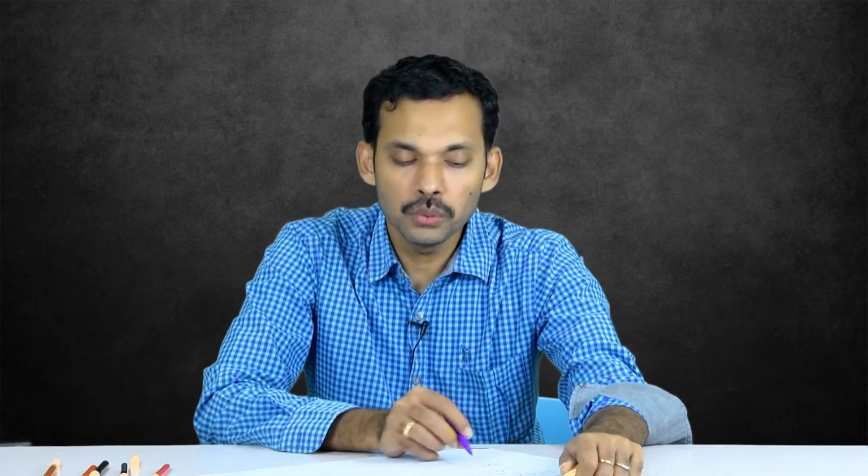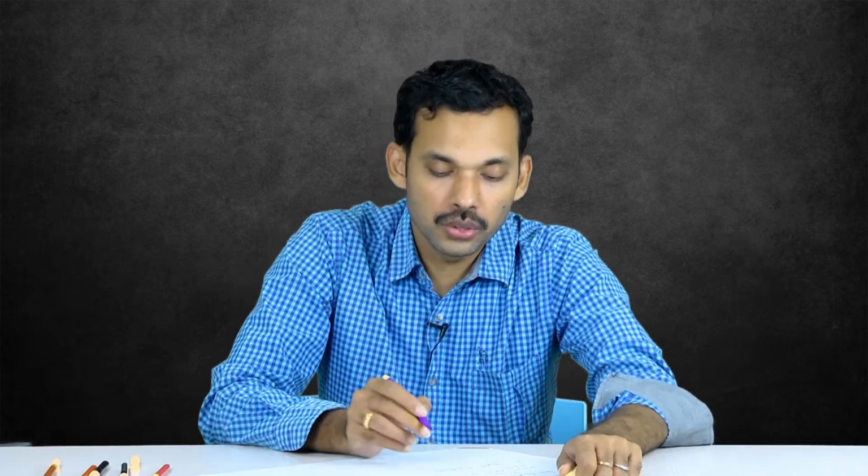We are going to get directly the digital pulse which we are going to feed inside a computer or a microcontroller or microprocessor kind of a mechanism, so that we can control the circuit easily. So this is a digital transducer where we don't need an ADC for the analog to digital conversion.